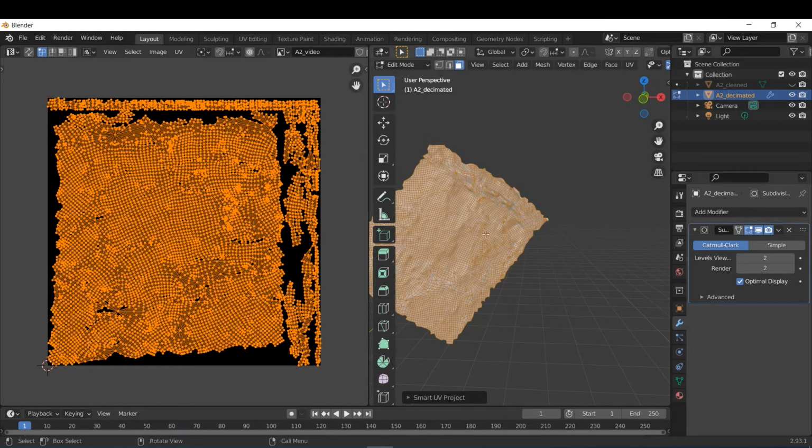And so now you can see that this mesh has been broken up into islands essentially and projected onto this image. Now this isn't necessarily the neatest way to do this, so you can see that this isn't all connected really. It's basically little pieces have been sliced off where they couldn't get it to work quite right. So if you wanted to texture this later based on this UV unwrap, that'd be quite difficult. But because it's normal maps and we are just using the software to get the normal map out, that's not such a bad thing here.